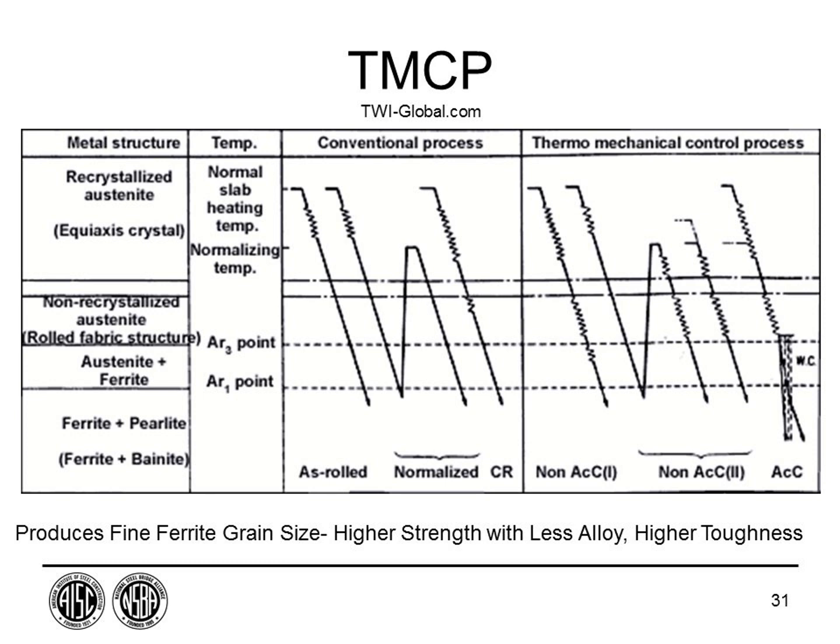In the conventional process we start up here at a high temperature, and these wiggly lines show where we're doing the roll forming, or rolling the plate. The conventional way would be to do that up in this austenitizing range, and then it would cool down, and we'd have the as-rolled plate.